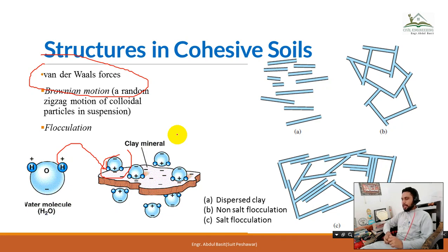Okay, so sometimes when the van der Waals forces overcome the negative charge of the clay, then the clay particles will come close to each other. Okay, sometimes the van der Waals forces will be less as compared to the negative charge repulsion of the clay particles. Then the clay particles will move away from each other.